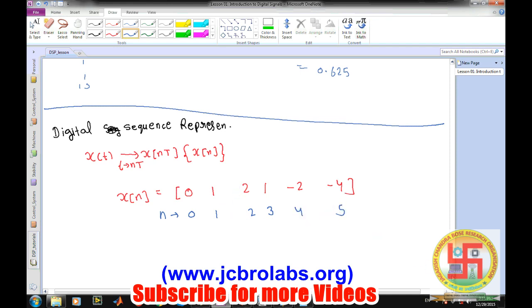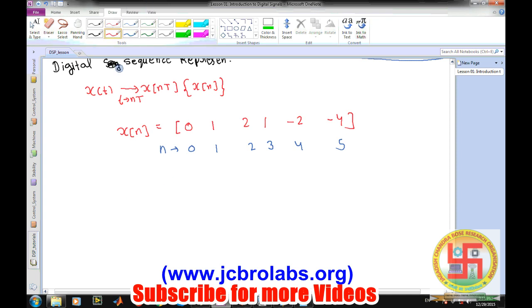If we want to specify what the index number is, we have to write it like this: minus 1, minus 4, 0, 2, 4, 1, and we specify an arrow. This arrow indicates that the 0 index starts from here. So if the 0 index is starting here, this index is minus 1, this index is minus 2, and then 1, 2, and 3. This is how we represent our digital sequence, and these are known as the indexes, and this is known as the sample value.